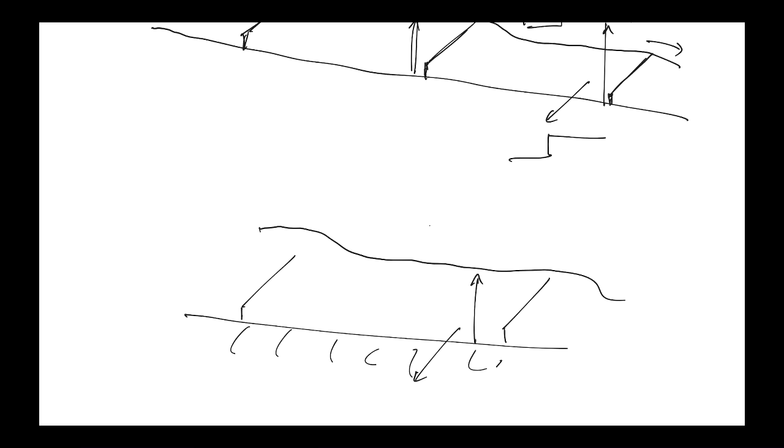They want flow. They don't just want a volume over any period of time. Often these are flood irrigators, right? And so they need a specified flow at the supply point to make sure that the water reaches the end of the paddock. So there's flow onto the farm and there's flow downstream. We're measuring the water level, comparing it to reference, and controlling the flow over the upstream gate.